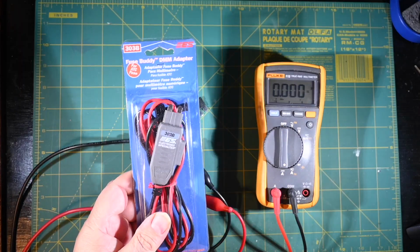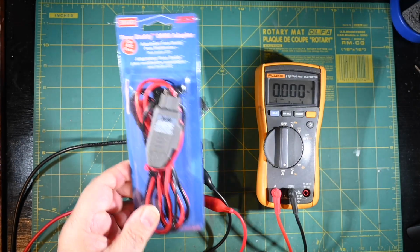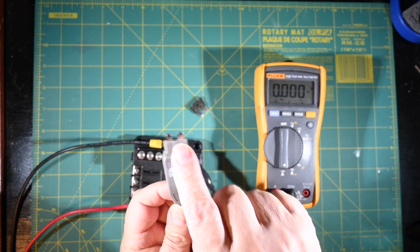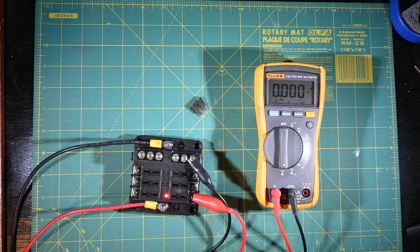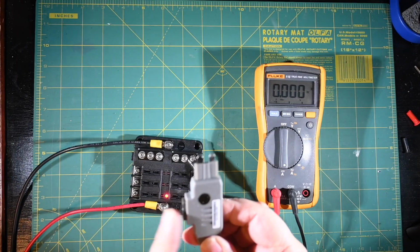Well, there's a product from a company called Electronic Specialties, and it is the Fuse Buddy digital multimeter adapter. It's not very expensive, but what it does is give you a fuse adapter for, in this particular case, ATO-ATC, and then the set of test leads that go directly into the meter. We also have a place for the fuse, so we don't lose fuse protection when we use this.